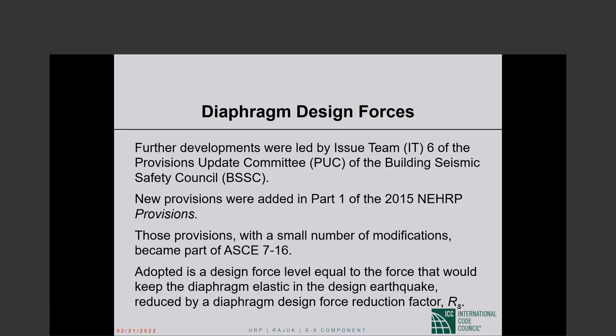This is like shear wall boundary elements. That does not require a thickened shear wall end. You can have a rectangular wall with specially confined boundary elements detailed within the thickness of the wall. It is the same thing. You can have beams, which are fine. They will act as collectors. If you don't have beams physically sticking below your slab, you can have just a bunch of reinforcing bars acting as collectors. Both ways is totally fine, and both are very common. So I think that answers at least 4 or 5 of your questions.